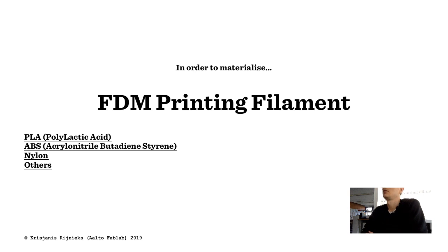Then, for the FDM printers, we need to talk about 3D printing filament. Here at the lab, we mostly use PLA because of the ventilation. If you try to melt other materials, it smells really bad, and it's probably not that healthy. There are some rolls of ABS, but when we tried to print ABS, it really stank. Nylon is also an option, but the same reasons apply.